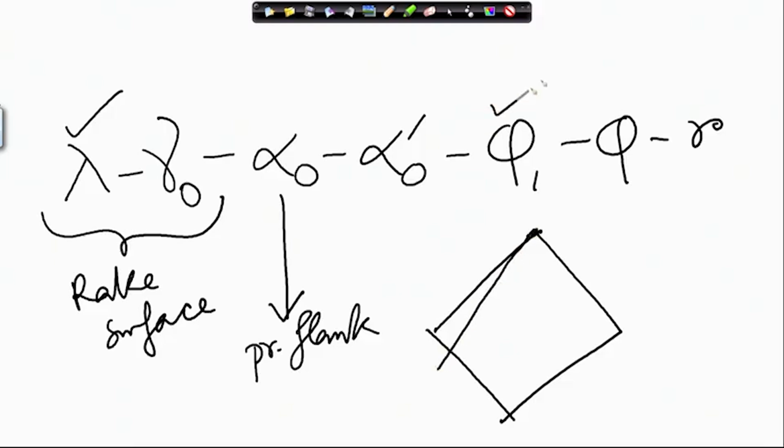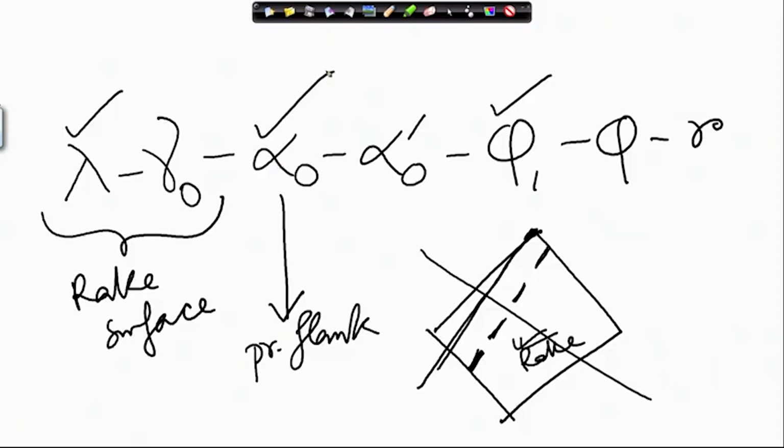So, I use up this information. So, this one is oriented in space, the rake surface. On that I use up this information to draw the main cutting edge. From the main cutting edge, in this direction I get the incline of the principal flank. I cannot see it from this side. I get the incline of the principal flank by this angle. So, I use this up also.